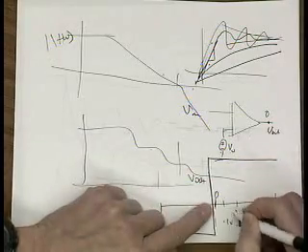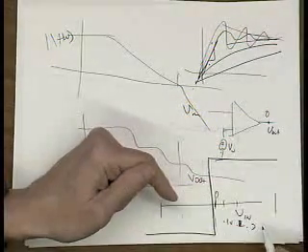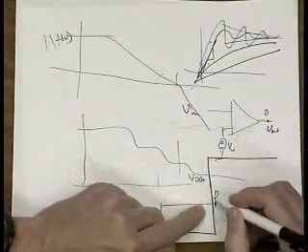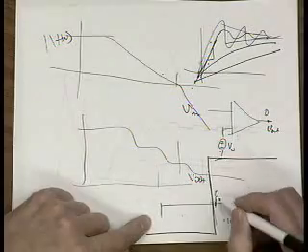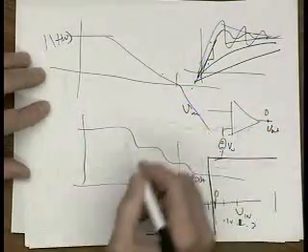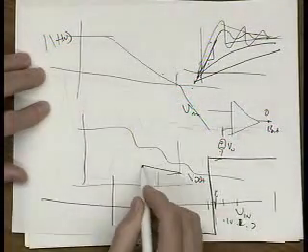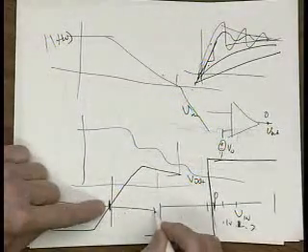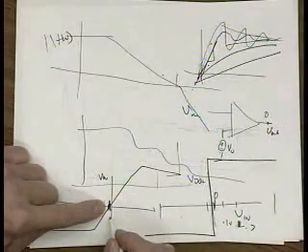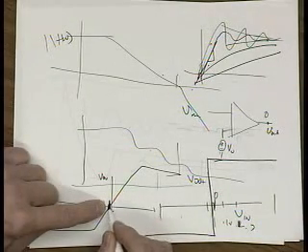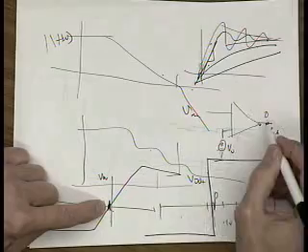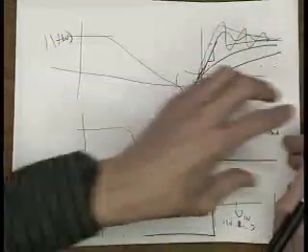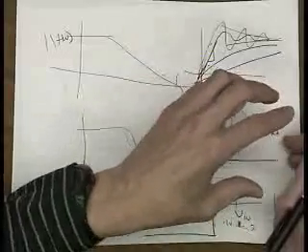Your job is to do a sweep like this, a V in versus V out, a DC sweep. Find this response. This is too sharp to figure out exactly where this is happening. Blow it up. Do it again. And then it'll finally begin to look like this. Then you can go in there and see, here's V out on this axis. You find out what V in is for V out equal to 0 volts. And you can bias this thing up so that the output is biased appropriately. And that means your DC biasing will be okay, or as good as it's going to get.